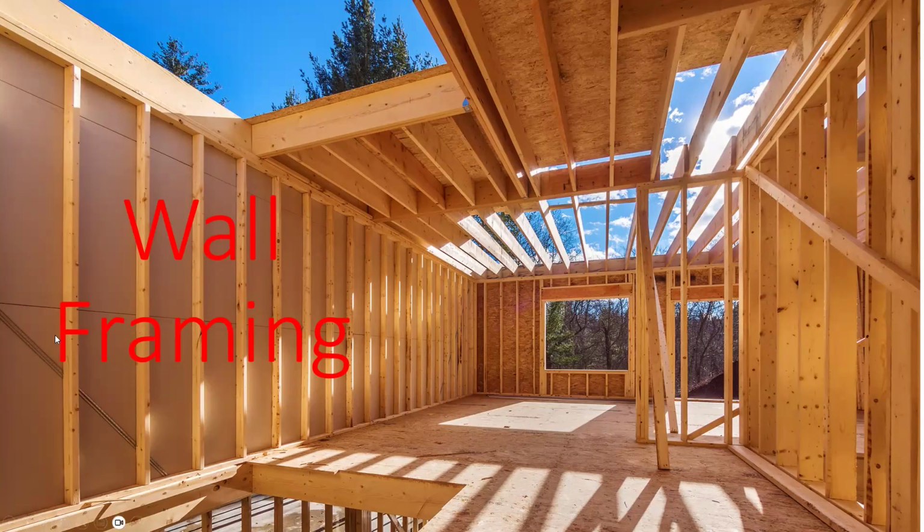But the reason I like this is you'll notice there's a metal brace here and there's a diagonal metal brace there. And those are providing the lateral stability in that direction. Those metal braces are like notched into the studs with a saw kerf. You can kind of even see that there, and then they're nailed into each stud. So by putting that diagonal in there, that stiffens that wall to keep it from wanting to tip over this way if the wind's blowing in towards us in the picture.